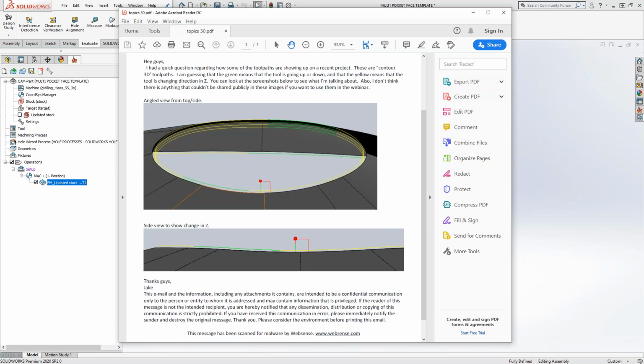Yep. So that's exactly what you would see when you use HSS. I haven't had a chance to watch the video, but the video is on the YouTube channel. But in HSS, it's a great example of what this means, because on the model, it might have a hole in it, but at that point in your toolpath, if you haven't had a chance to remove that material and you're going to do a gaps along the cut follow surfaces just to account for that, the wireframe will still show it as green. Like Kevin just said, it's skipping over that gap by doing a feed move. In reality, it's cutting material, but in the toolpath, it's just assuming that it's jumping a gap, so it gives you the green color instead of, in this case, the yellow color.